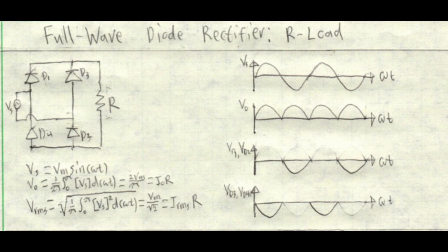Wall current is AC, which means the voltage alternates between positive and negative, and the current flow alternates between two directions. However, batteries need DC. Diodes only allow current to flow when the voltage is positive. The bridge configuration from my circuit diagram only lets current flow through the load in one direction. The top graph is the AC input, the one below is the DC output.